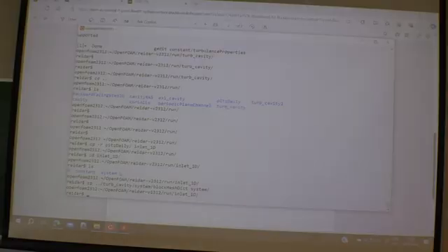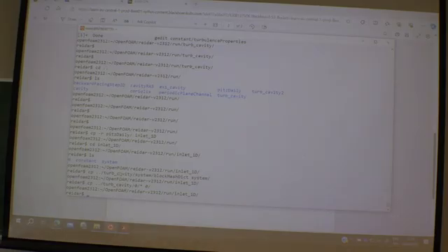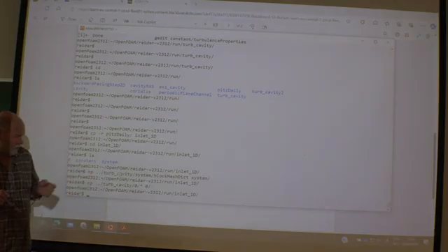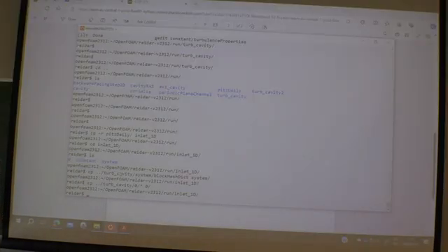Then at the same time we can actually copy most of the zero folders as well. Let's take the entire zero folder. cp, turbulent cavity, zero folder, all the files there into my zero folder here, like that. So now I've copied a lot of the setup for the turbulent cavity case, mostly. Let's start with the mesh.